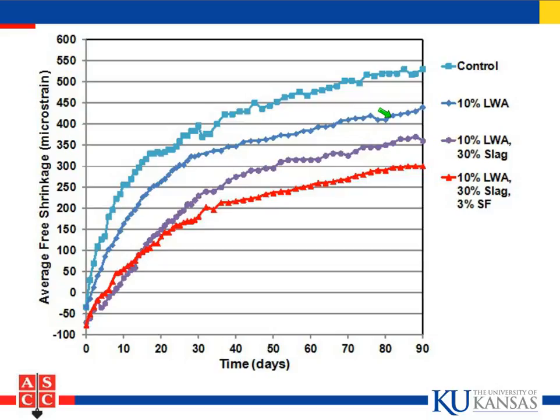Now, the water-cementitious material ratios in these cases were not particularly low. Internal curing has separate advantages for really low water-cement ratios. But in this case, the water-cement ratio was 0.45, so very regular material. We don't have to worry about something called autogenous shrinkage. But you can see the water coming out helped a lot.